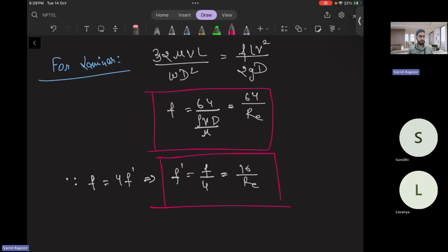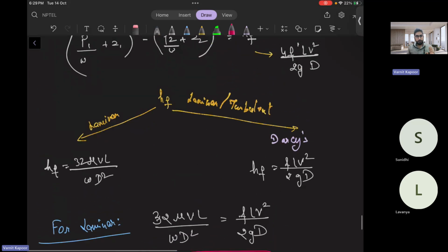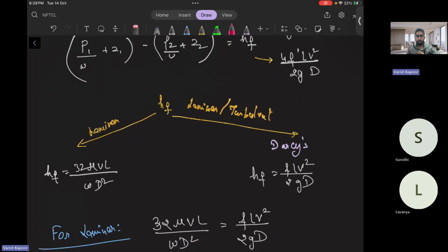This is the friction coefficient value. Now the point might come that for viscous flow, the Bernoulli equation is not valid. That's why we incorporated the Navier-Stokes equations, from which Hagen-Poiseuille, plane Poiseuille and Couette flow come out.